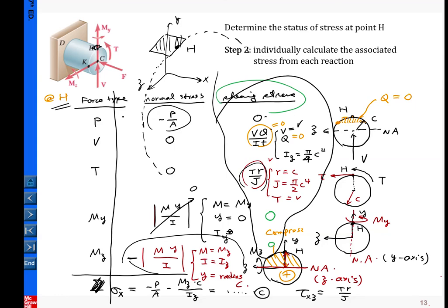Okay, so hopefully you see what I'm doing here. So that's the parameters of the sections. Okay, so that's going here. So now we have determined the normal stress, which is negative. So this is sigma x, whatever we calculated here. Okay, and tau xz, if you map this information to here, is pointing this way. That is tau xz here. So again, if you complete the whole drawing, this is the stress, and it would be like this.